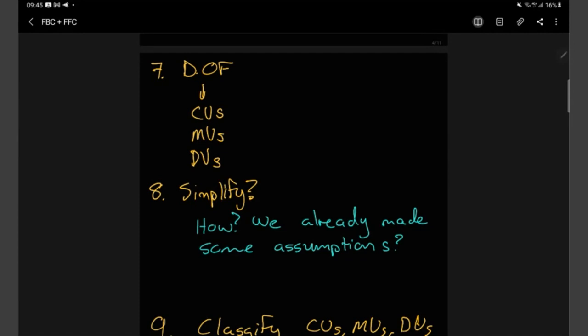Now we come to a point where we sit with a number of equations. We do some simulations of that or verify it against plant data or known data. And we realize, oh, that only has like a 0.001% effect on our actual set of controlled variables that we are looking at. Now we can say, well, let's just scratch that one because it's only complicating the set of equations, our model, and there's no real reason. We don't want to work in inaccuracies of 0.001%. We are engineers, we aren't chemists or physicists.